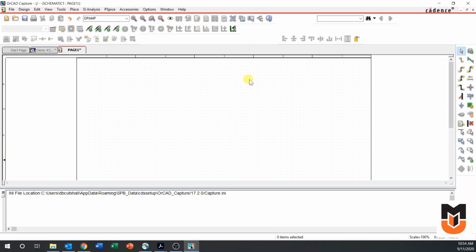In this video, we're going to look at how to do op-amp circuits in PSpice. This is going to be relevant to our second lab in ENG 301. I've already created a blank project here, and it's important to note that you want to create a project as opposed to a design, otherwise you're not going to have all of the simulation capabilities.